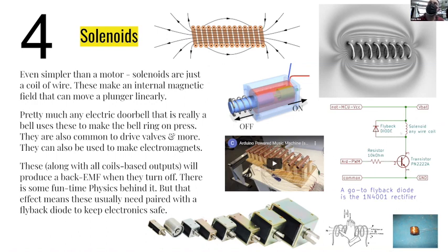But the circuit for solenoids is fascinating. Their symbol is just a coil, like a series of loops. And so you've got a transistor to turn them on and off, and then you can run them at whatever voltage your supply is. So you don't need to power them directly from the Arduino. It's probably actually better if you don't power them directly from the Arduino, because they can pull a bunch of power, and then because they're sort of raw electronics pieces, they also will do something when they turn off.